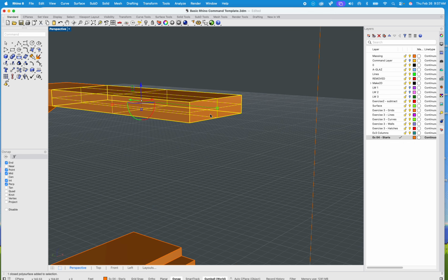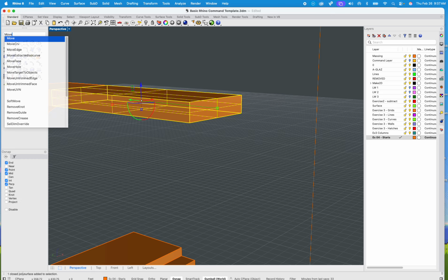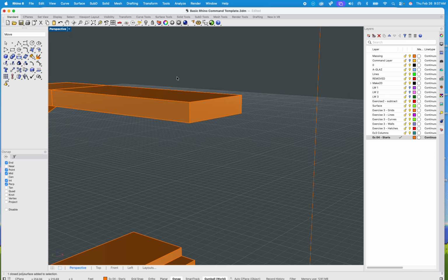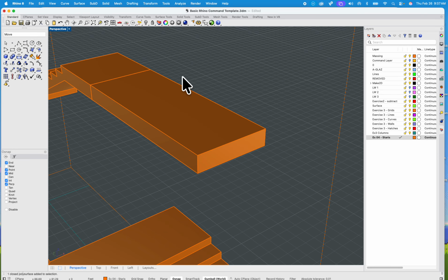I'm going to move that face up because I do want to show you how to make a ramp, at least in 2 different ways. The best way I think to make a ramp is the simple way, so just moving the face up, 6 inches, 12 inches, depending on how long this is. And maybe we need to know how long it is. So I'm going to do DIM for dimension, not move dimension, but dimension. I'm going to click on 2 points. And voila, 10 feet, or 10 units. And I know that my units are in feet, so I do have 10.